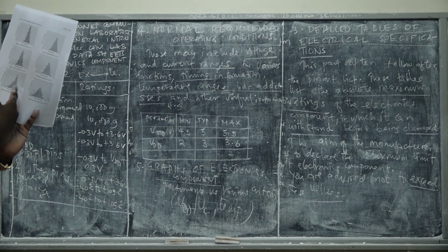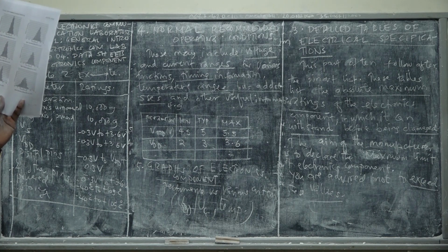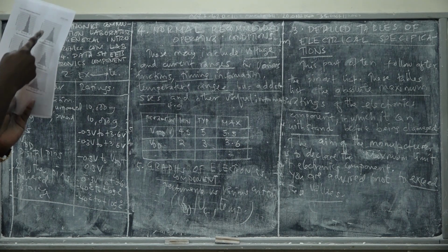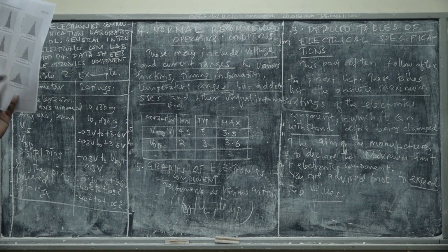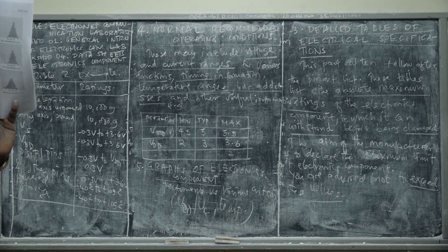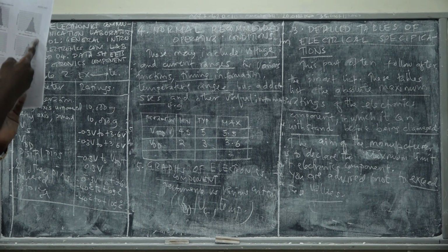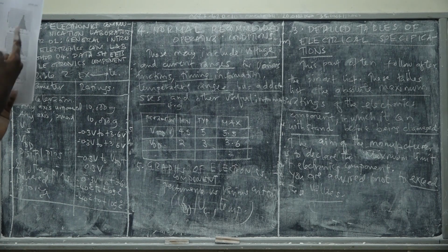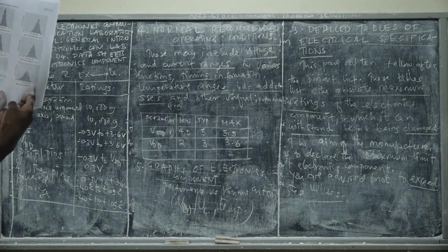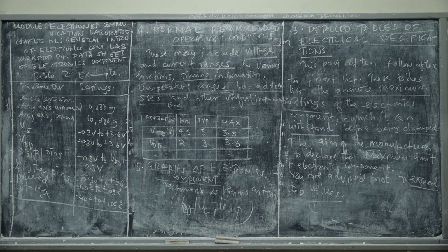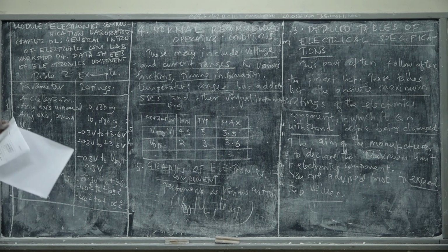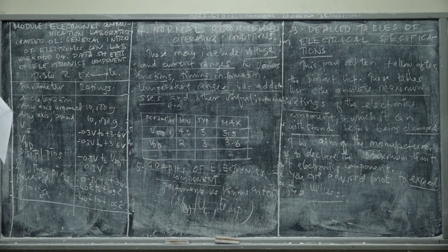Right? Then the offset temperature, it is what? 25 degrees centigrade. Again, here we also have the other 3 axes. But remember, here the supply voltage is 2.5 volt. Right? When you increase the supply voltage to 3.3 volt, this is the histogram for x-axis, y-axis, z-axis. You see the difference? That is page 7. Then page 8.